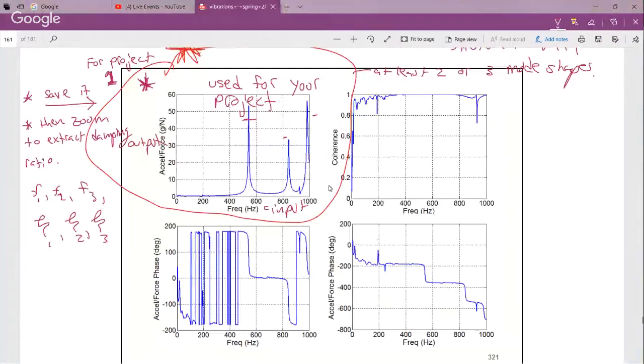Let me give you an example. Let's say I have a bolted joint, and I'm measuring the force in that joint, but I'm not really interested in 1,000 pounds of preload. I'm interested in the fluctuation about 1,000 pounds. Would I set my input channel to DC or AC? AC. AC.